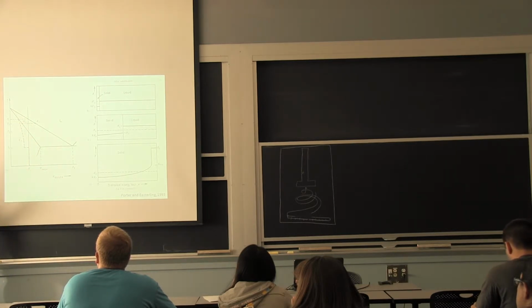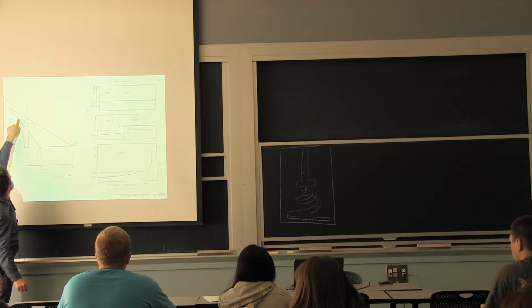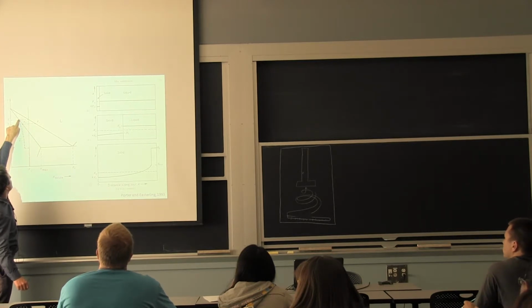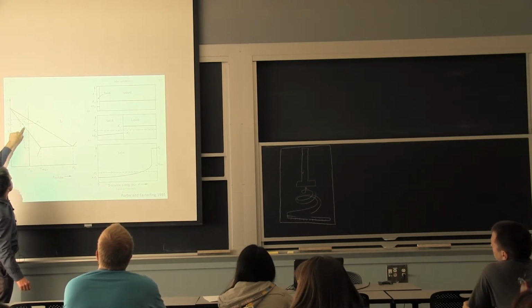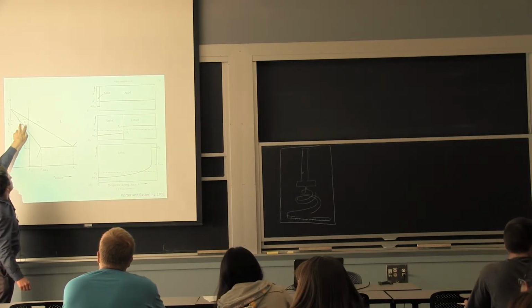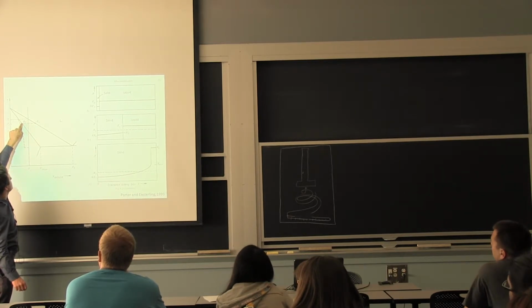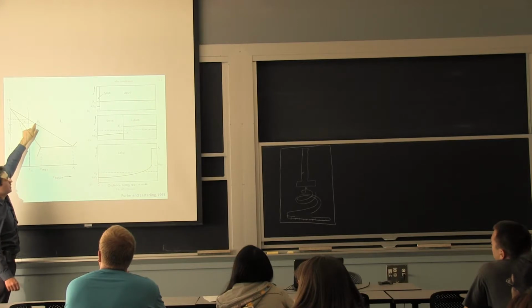And even if you cool it down very, very slowly, what's going to happen at this temperature, well, they have this example here, so we can use that. But starting here, you'll form solid with this composition, as opposed to the nominal composition. So all of a sudden, you have a different composition in what you are solidifying and what is your liquid.